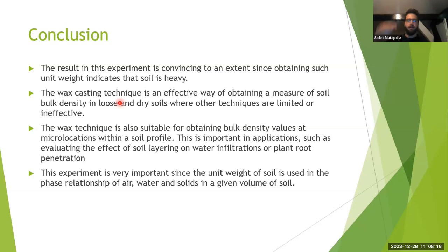If your layer is 1 or 2 meters and you're really shallow, near the surface, and that layer starts acting like nothing, you're going to have a collapse because your layer of bearing soil lost any kind of mechanical properties.